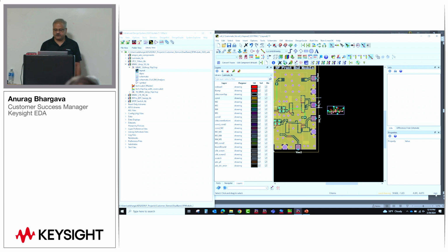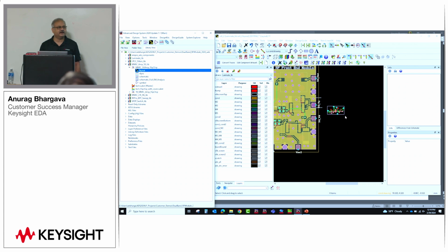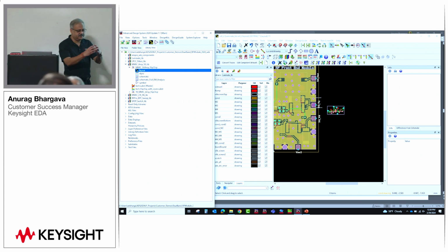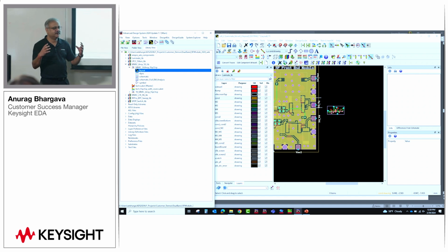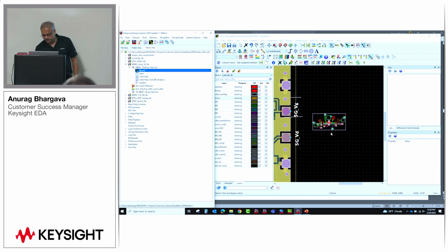Now, the key thing you notice on the bottom right-hand side: the laminate is being designed in millimeter technology. It has all preferences set for millimeter. But when I dragged and dropped that IC, and if I open the layout of the IC, if you refer to the lower right, it's micron, right? And usually all ICs are micron. But when I drag and drop that IC, it retained its technology. It retains its units. It doesn't blow out of proportion to scale as per mm. It retained everything.